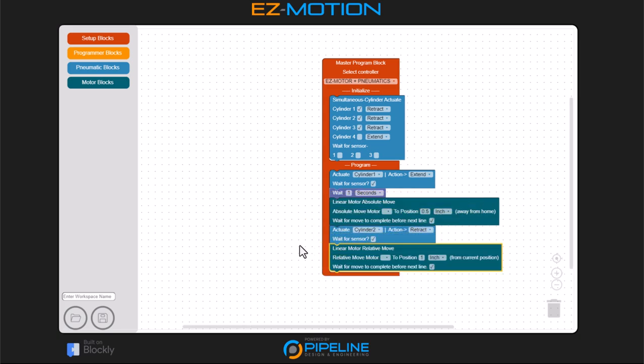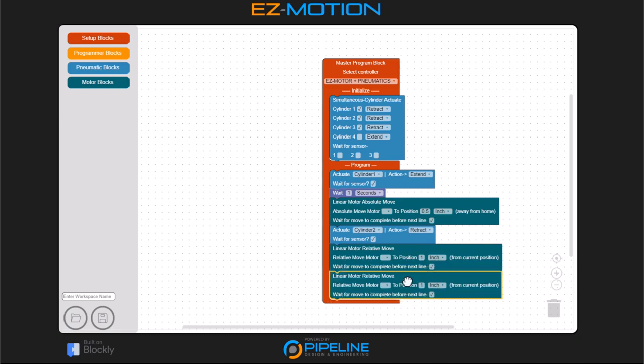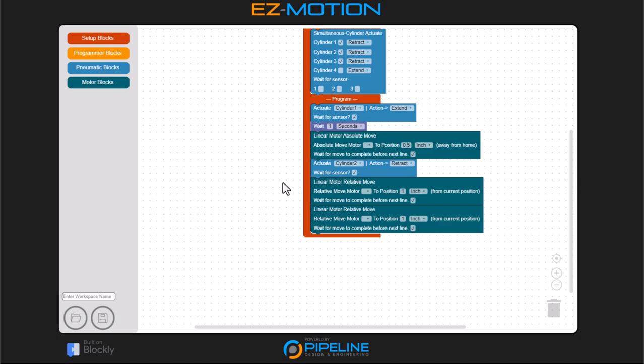For convenience, function blocks can be duplicated using the typical Ctrl-C and Ctrl-V keyboard shortcuts. Simply click the function block to highlight it. Press Ctrl-C, then press Ctrl-V. Any settings that have been configured in the block will be maintained when it's duplicated. Only a single function block may be copied and pasted at a time.